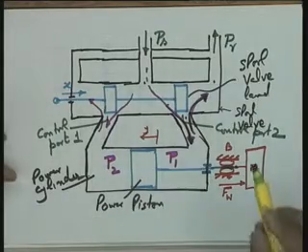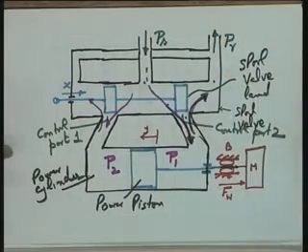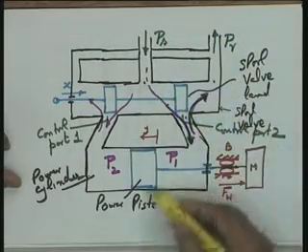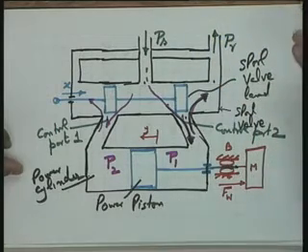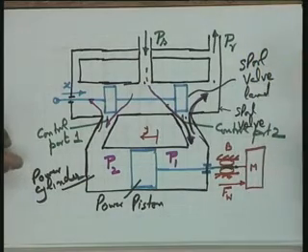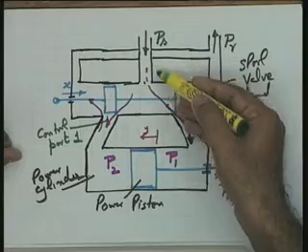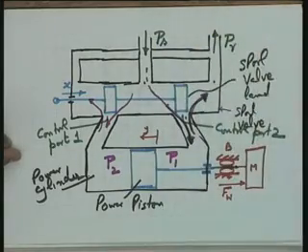Please see, Ps is the supply pressure and PR is the drain pressure. Can you account for the total pressure? Keep in mind that pressure is analogous to voltage if you use the concept of analogy. So, you can apply Kirchhoff's voltage law to see the total voltage drops. So, in this particular case, I want you to travel along the route of fluid flow and keep the pressure drops in mind and give me the balance of pressure drops. So, move along the fluid flow.